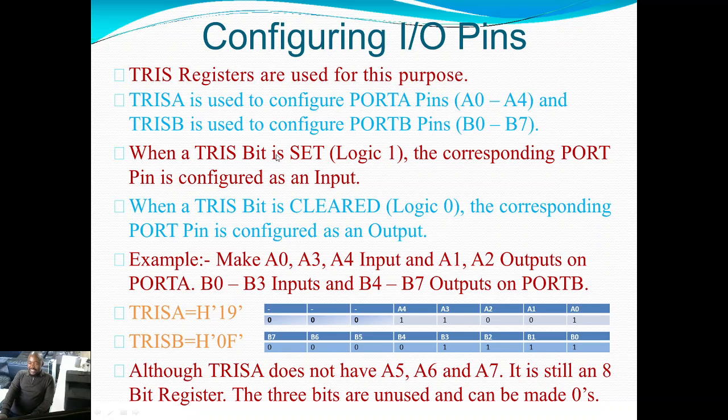Right. When a TRIS bit is set, either TRIS A or B, when any TRIS bit is set, meaning the logic level of that bit is made 1, logic 1, the corresponding port pin is configured as an input.